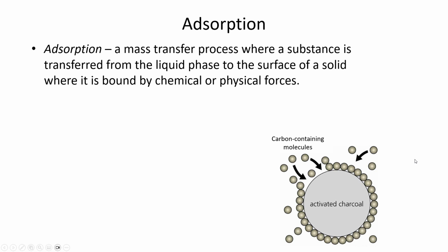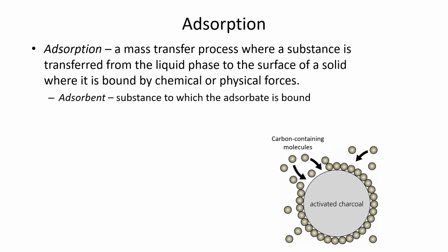And adsorption is just that the carbon-containing molecules are more greatly attracted to the activated charcoal surface than they are to staying in solution. And so the adsorbent is the activated charcoal that maybe, during certain seasonal periods, water would be flowing through a treatment plant with activated charcoal.